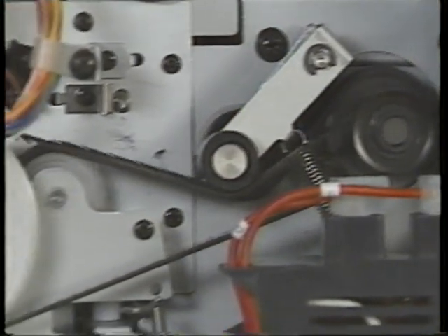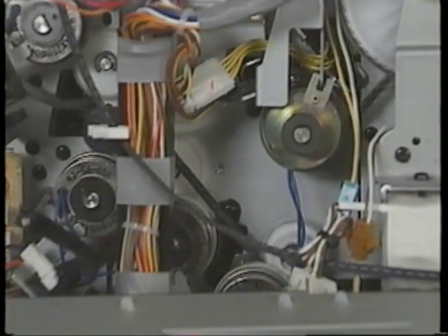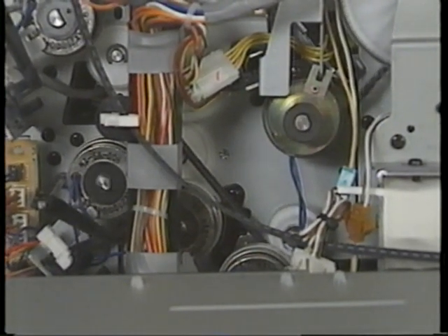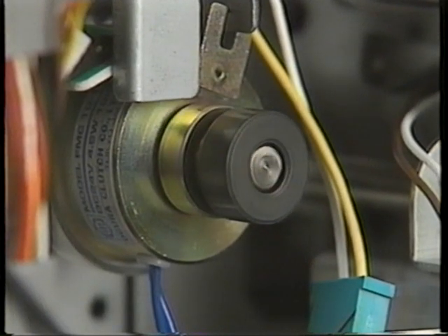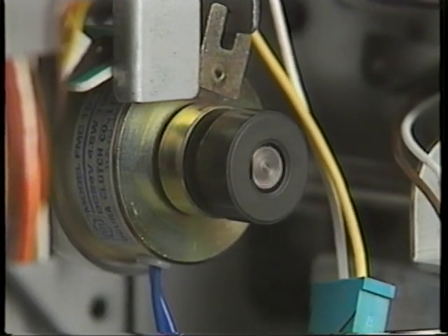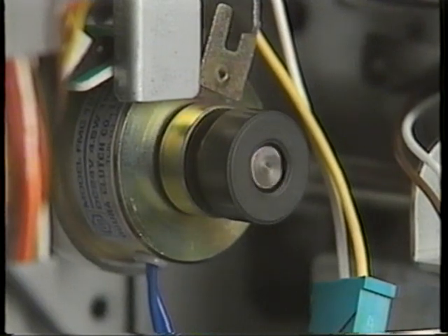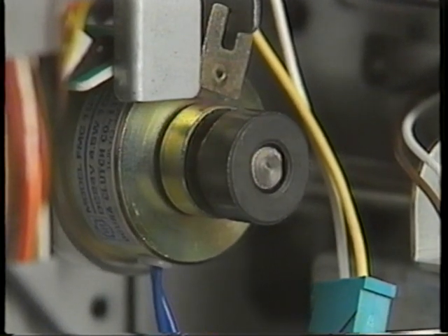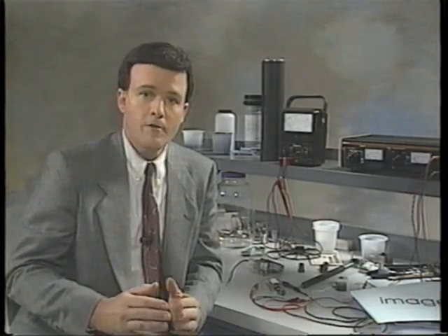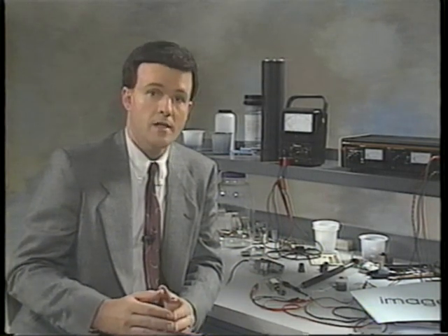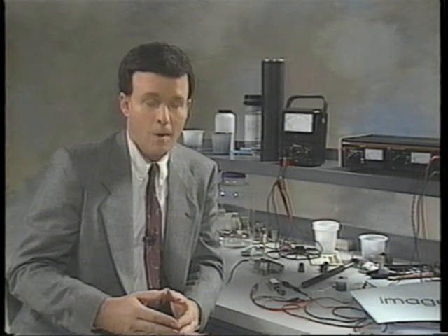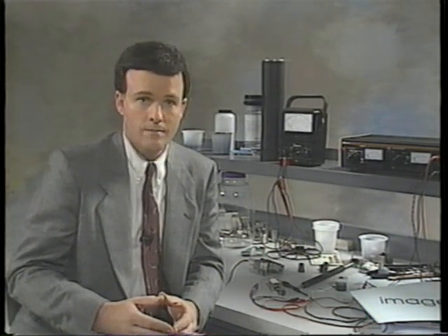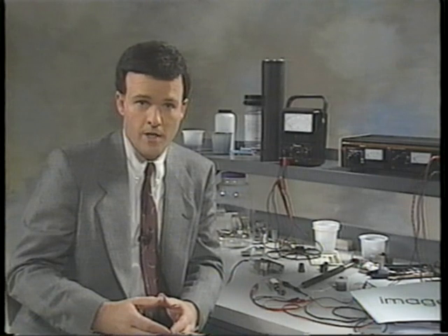In most copiers, the drive for paper feed components comes from the main motor and is transmitted to each roller by a system of belts and gears. Since feed rollers have to supply paper according to the precise timing of a copy cycle, they're usually driven through some kind of clutch. A clutch is a type of mechanical link between two different assemblies that can make them engage or disengage as required. Most of us are familiar with the clutch in a car. It provides the link between the engine and transmission.